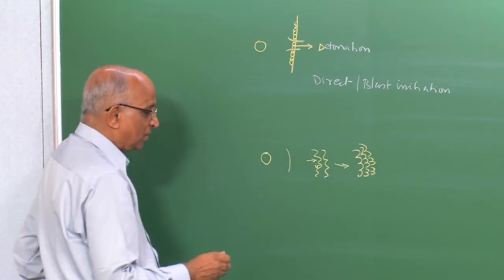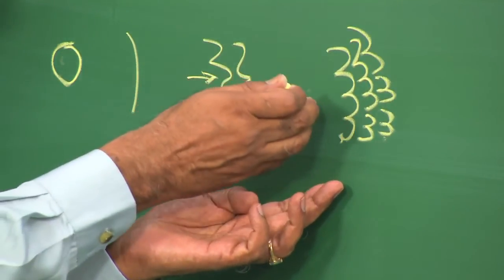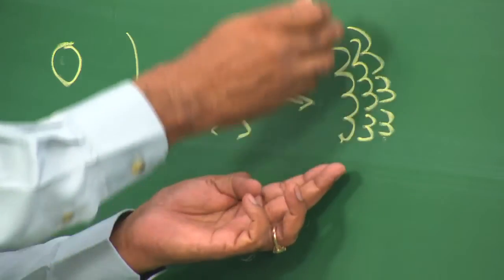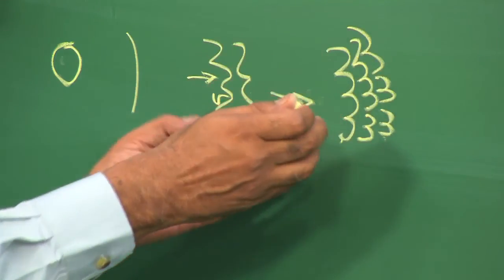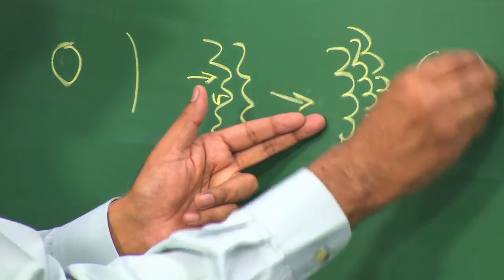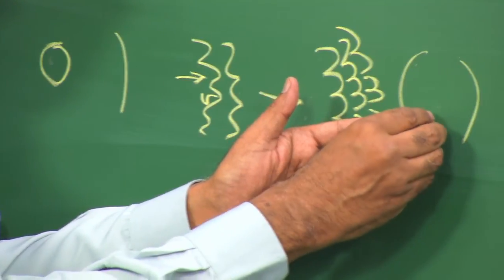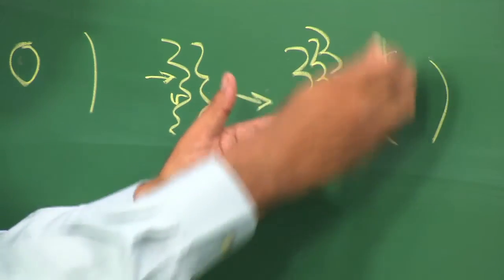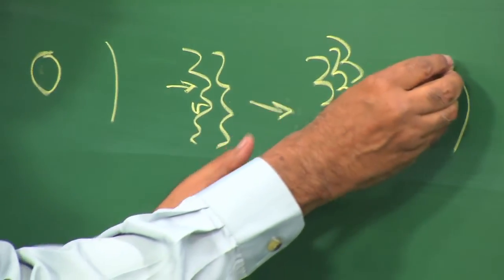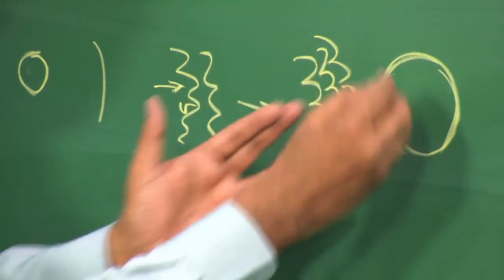We also saw some pictures saying that whenever I have blockages or wall effects, since the velocities of the unburned gases ahead are already large, I create shock structures, or maybe expansion waves, maybe weak shocks within it, which make the turbulence so high. These are the unburned gases in which the concentrations are high. Whenever something starts burning, because of the high turbulent intensity, the chains which are formed are also terribly fluctuating or terribly mixing, and therefore I could have a zone of gases formed ahead of the flame which goes into something like a constant volume combustion.